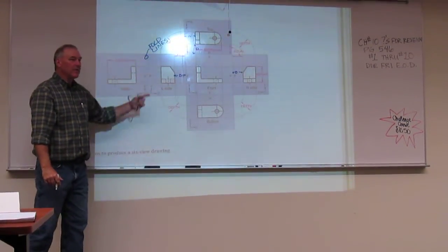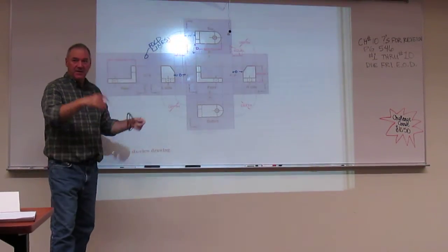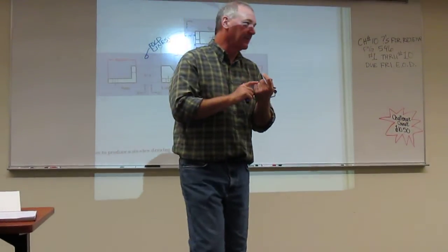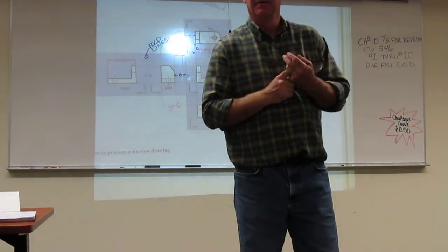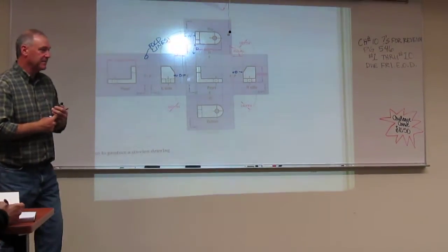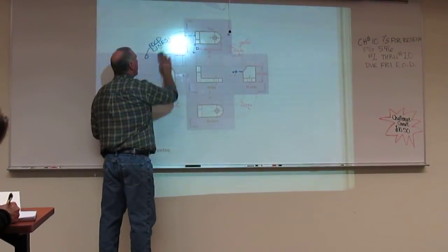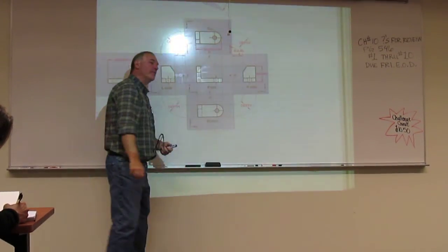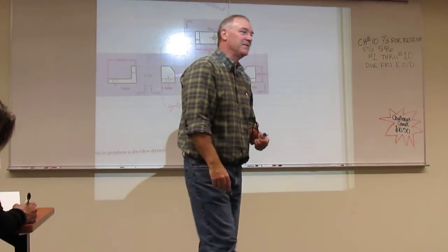So fold lines, we aren't going to use them right now, but later in the year, we're going to be using fold lines when we get into things called auxiliary views for oblique planes, these types of things. So fold lines are used to transmit dimensions between views. Those dimensions would not be put on a final drawing, but you would use them to produce the drawing.